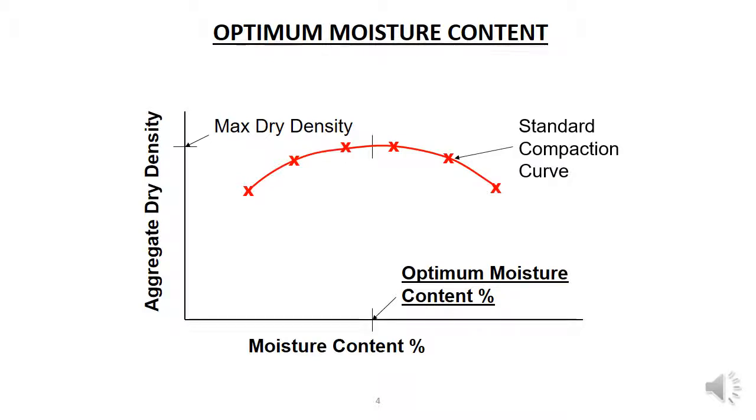There are charts that allow us to correlate dry density with strength, and so the designer can figure out what strength the aggregate will have in service if it has that particular maximum dry density. This is used in pavement design.